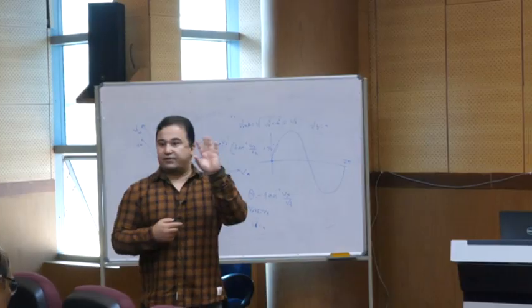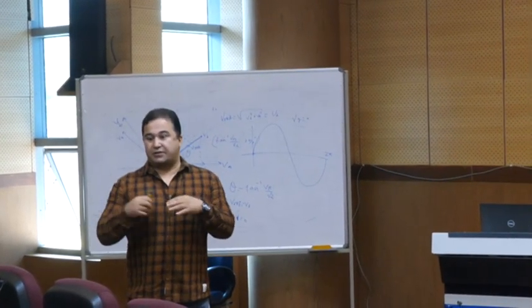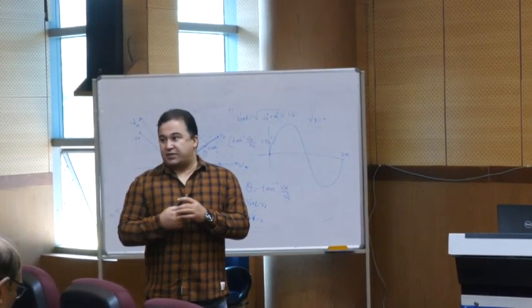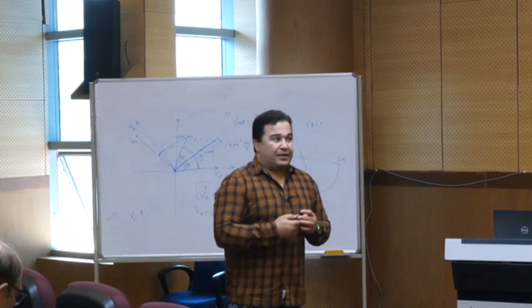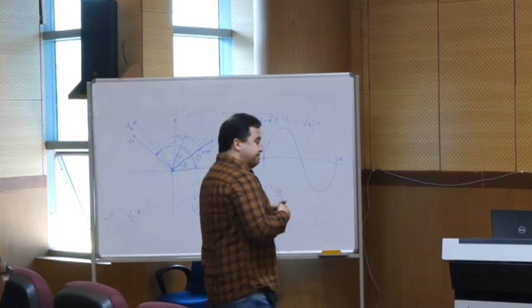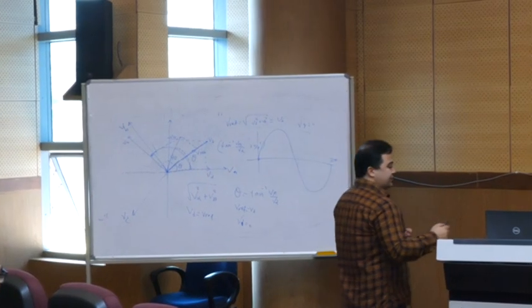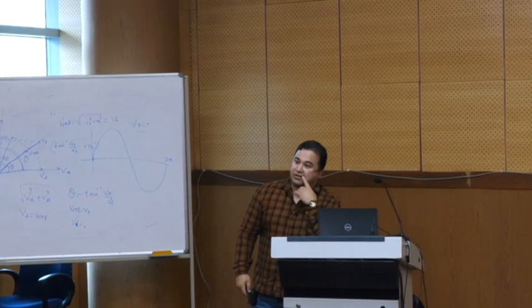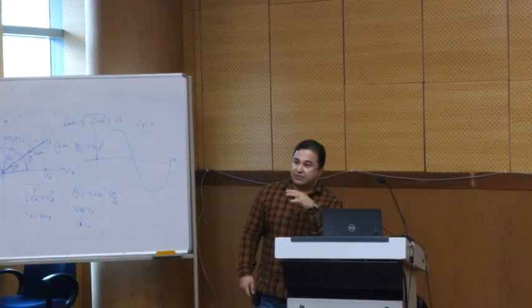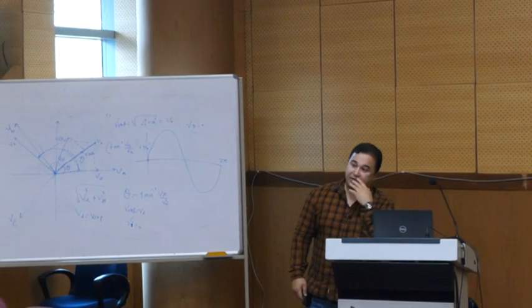For example, with alpha beta, you can go from the positive and negative sequence, and then you play with the negative part and the positive part, separate them, create the reference based on that, and compensate. There are several methods, but probably one of the easiest ways is to use the Park transformation, and then you have the flexibility to apply it to different applications.